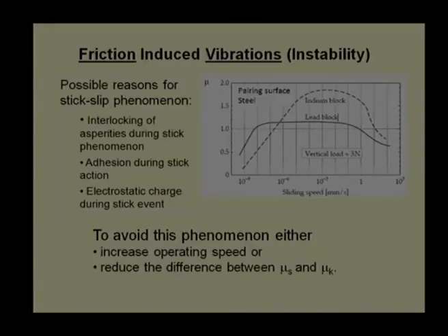I can give a very typical example of a journal bearing. When a journal bearing, particularly under radial load, operates in the fully developed condition, the coefficient of friction is very low, maybe say 0.001. But during start and stop, if there is no friction modifier available, then the starting coefficient of friction will be very high, maybe 0.1 or 0.15.